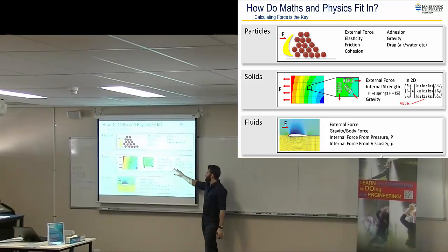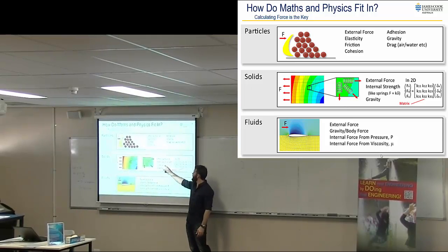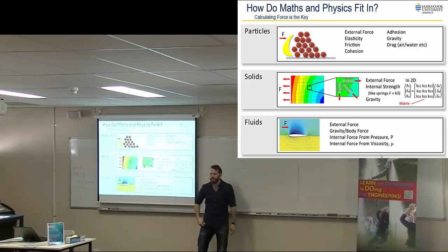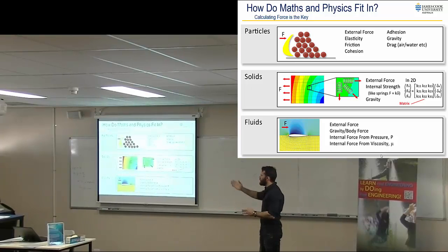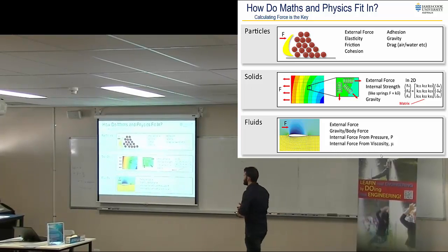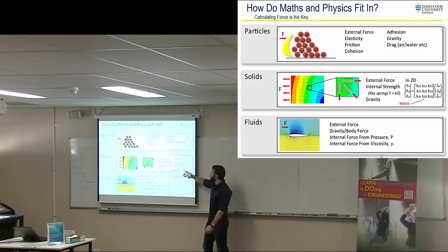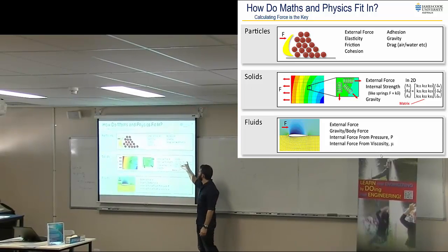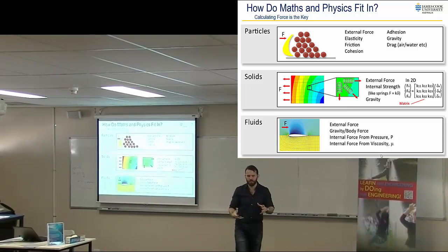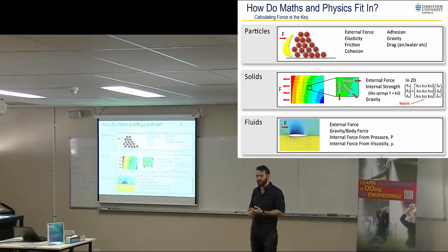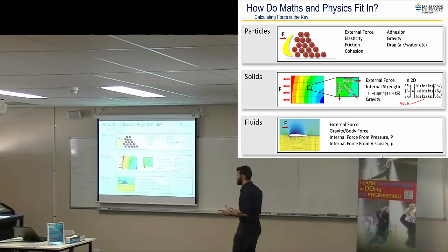And another thing that we actually use when you're talking about a stiffness equation in 2D, F equals K delta, so spring stiffness times how much the spring stretches. When you've got one of these solids, we actually have similar spring stiffness equations, but in 3 dimensions, and that's where matrices come into it. And we use a lot of matrices, in particularly these solid ones, where we have force in 3 dimensions and a matrix multiplied by a vector of those displacements in the 3 dimensions. And it gets a lot more complicated than that, but that's a very simple illustration of where matrices actually get used in exactly the same circumstance.